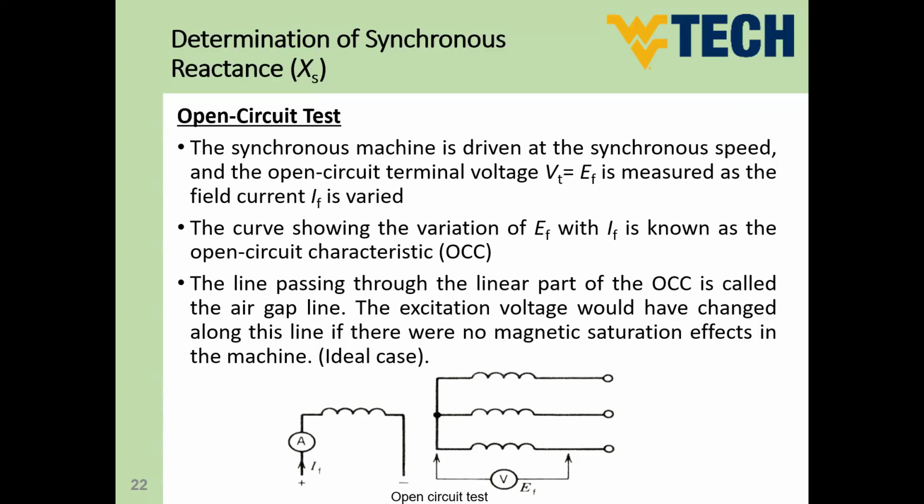So what is the synchronous reactance of a synchronous machine? Sorry, how to identify the synchronous reactance of the synchronous machine? This can be done using what's called open circuit and short circuit tests. I'm gonna quickly discuss this in our class today, and in the next session, we will solve some numerical examples on the parameters identification of the synchronous machine.